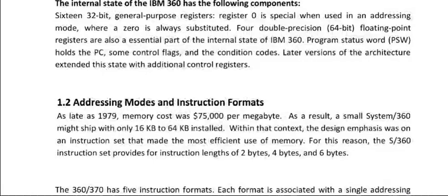With that context, the design emphasis was on an instruction set that made the most efficient use of memory. For this reason, the S360 instruction set provides for instruction lengths of 2 bytes, 4 bytes and 6 bytes. We will see which instruction formats utilizes how many bytes next.